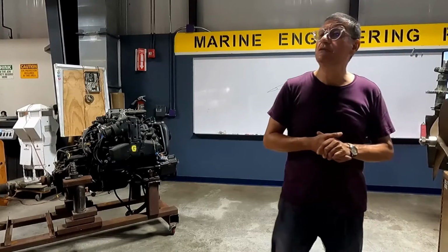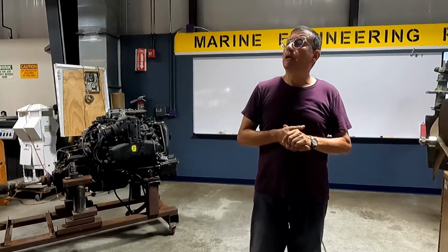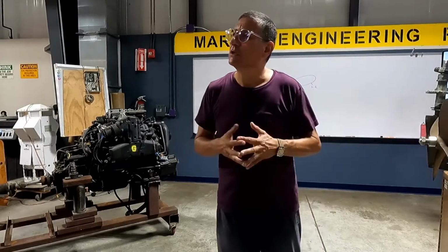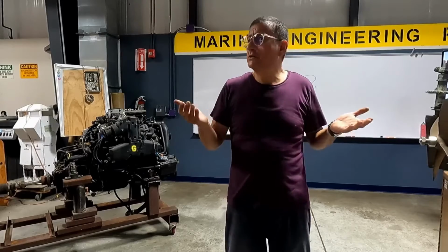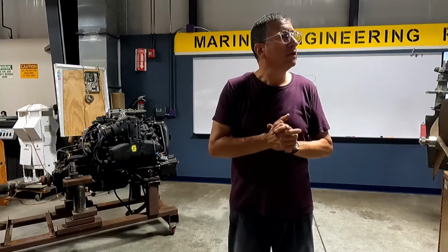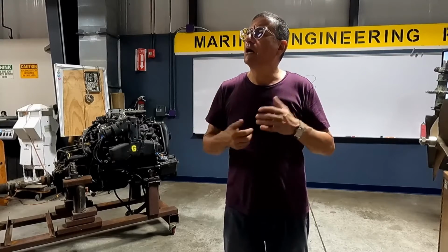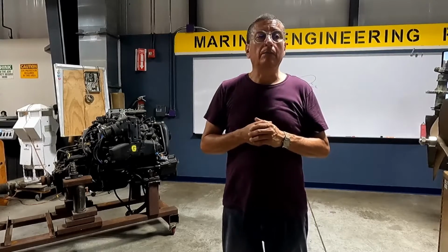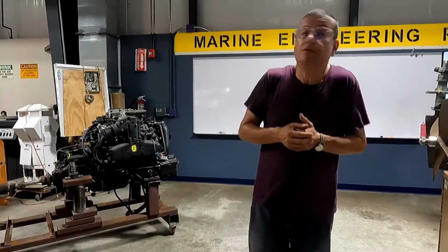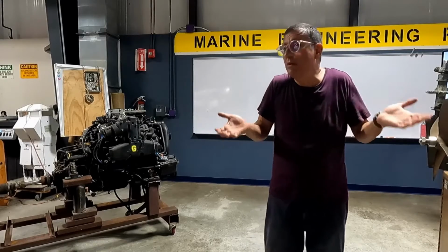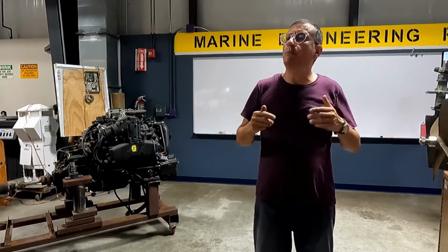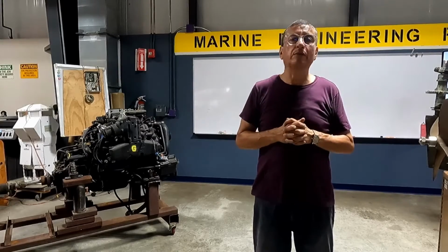And in some cases, later we are going to talk about that. The captain complained about vibration. And you check the propellers, the blades look in good condition. They look great. However, they feel vibration. In that case, I recommend removing the propeller and balancing the propeller. It doesn't matter if the propeller is in good condition, it is probably unbalanced. And normally it's unbalanced. After you balance the propeller, you feel better performance of the boat.